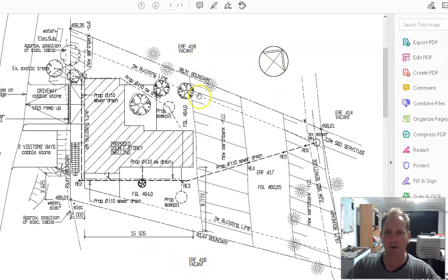Your property, your adjacent sites should be mentioned. A site plan isn't necessarily a setting out plan, but if it is, you should have dimensions from those little metal corner beacons to the corners of your building, so the builder can set out the building accurately. Water meter, electrical substation, anything else that's of interest on the whole site.